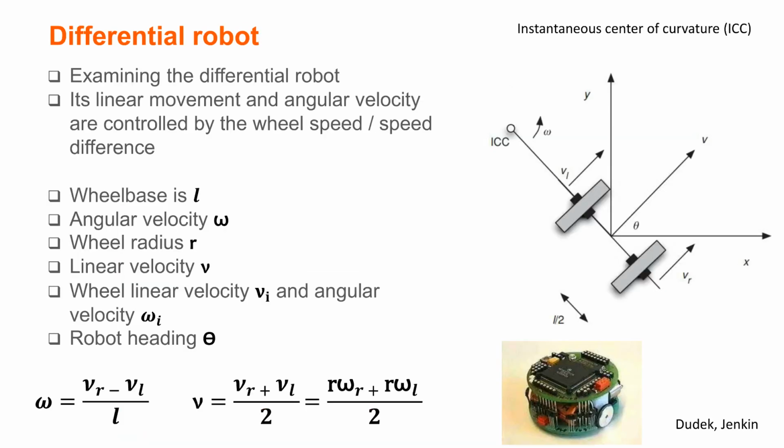Differential drive robots use two independently controlled wheels to move. The robot's direction is determined by wheel radius R, which affects speed and torque; wheel separation L, which determines turning ability; and wheel speeds V_R and V_L. Adjusting speeds changes movement direction. For example, if both wheels move at the same speed, the robot moves straight. If one wheel moves faster, the robot turns.